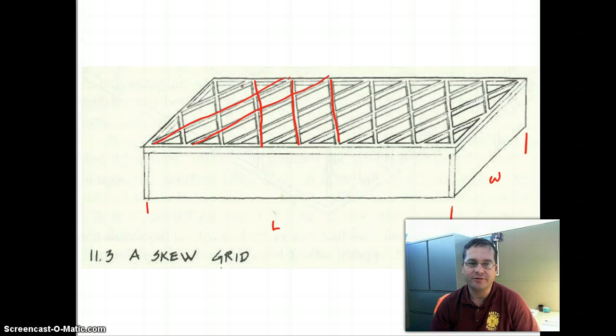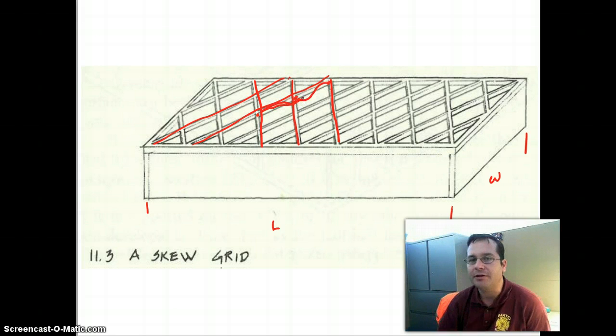Again, common material for this would be reinforced concrete. Reinforced concrete works well because we want to make these joints rigid so that basically any movement of the joint causes twisting in all of the surrounding components. And we've talked, I think, in other chapters about this idea that these will develop this kind of inflection point behavior where each surrounding component gets twisted into an S shape. So reinforced concrete works well for that. It certainly could be of welded steel construction, although that would be expensive. And occasionally you will see these constructed of wood, commonly called a lamella type roof if it's constructed of wood.